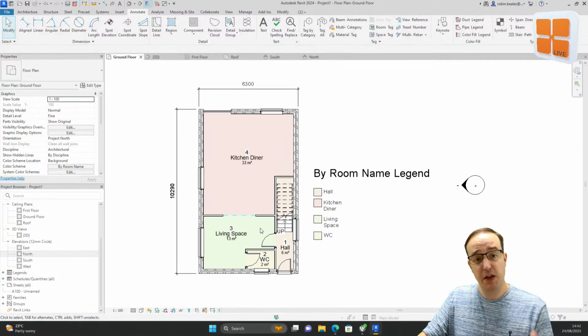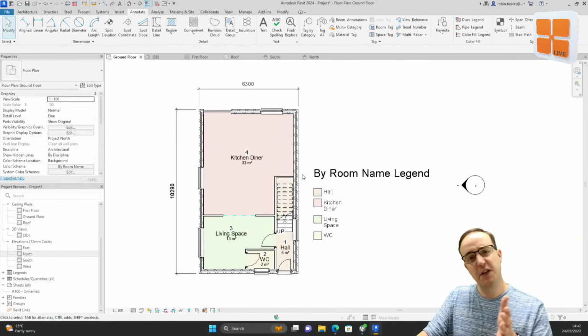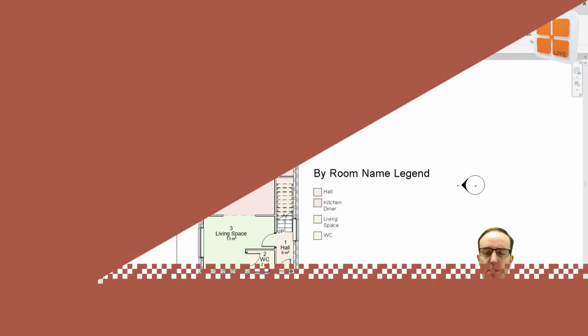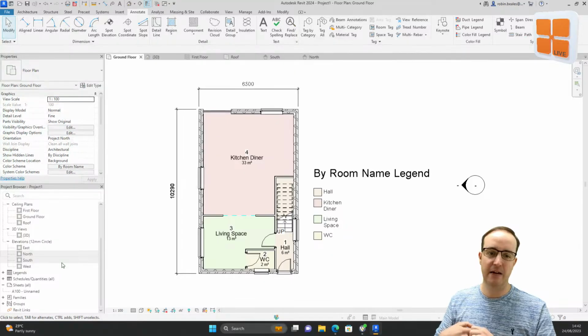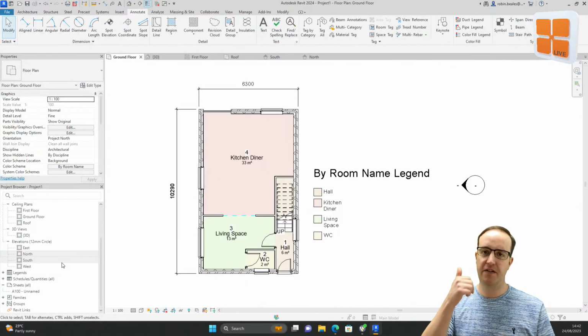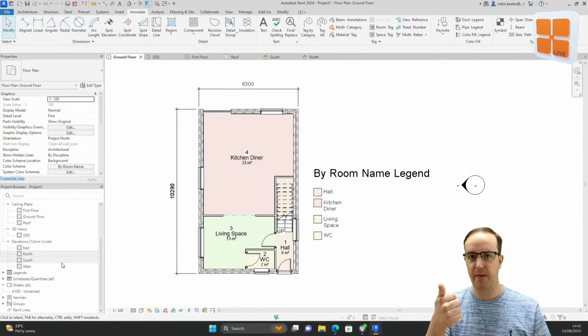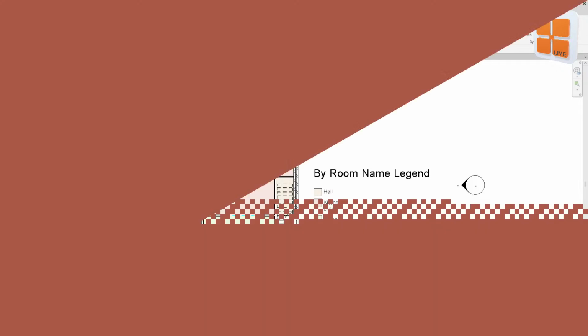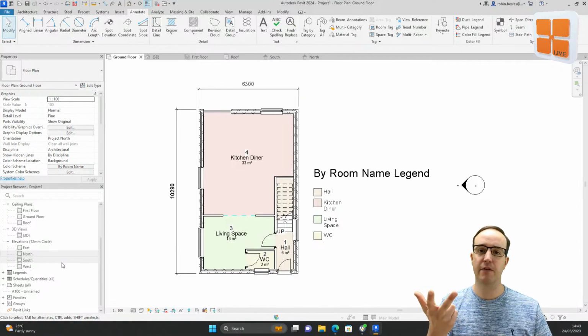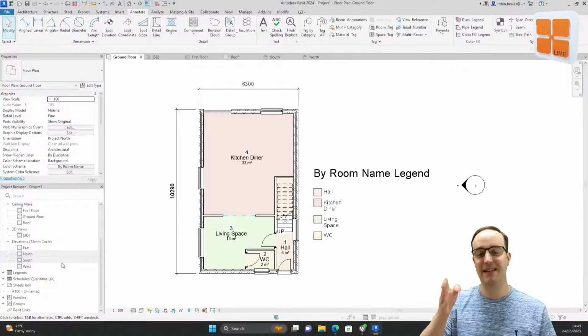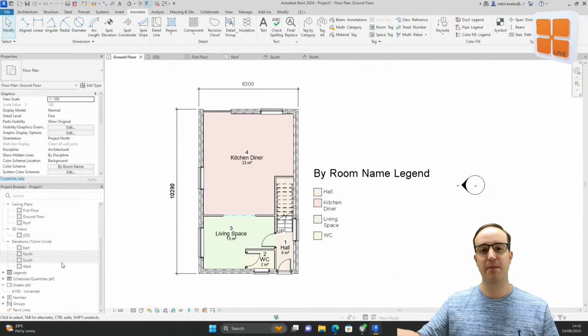Now, everything you see in Revit is what you get. So when you have a view, what you see is what will print. But very differently in Revit, we have one model, but we can have as many views as we need. So on this floor plan, if you wanted one that you just use for designing, maybe one showing the floor plan and FF&E, maybe one with room layouts or zone layouts, we can duplicate the view 3 times to have 3 different views of the same thing.